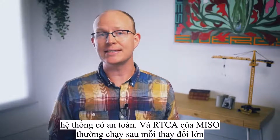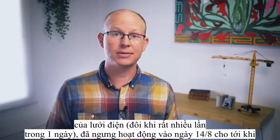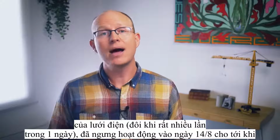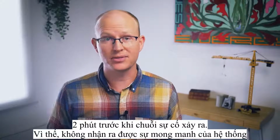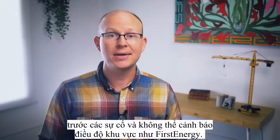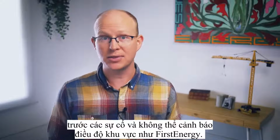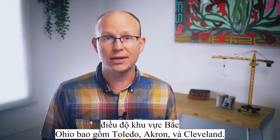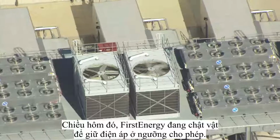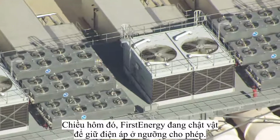And MISO's RTCA tool, which was usually run after every major change in grid conditions, sometimes several times per day, was offline on August 14th up until around 2 minutes before the start of the cascade. That means they couldn't see their vulnerability to outages, and they couldn't issue warnings to their control area operators, including First Energy, the operator of a control area in northern Ohio, including Toledo, Akron, and Cleveland. That afternoon, First Energy was struggling to maintain adequate voltage within their area.